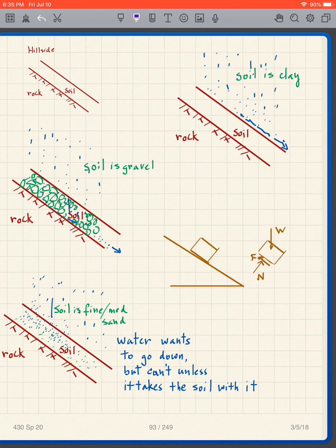I want you to be aware of the impact of water from rains on both slope stability and our retaining walls. We like to have these free draining soils. That's our best bet. And let me make one other comment.